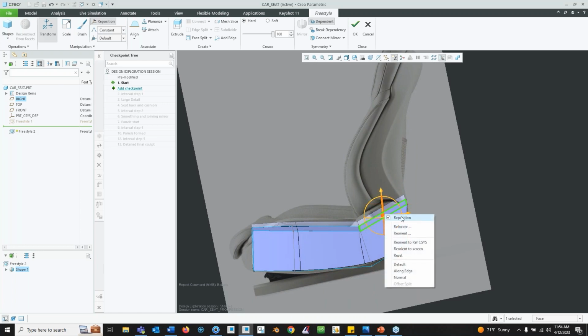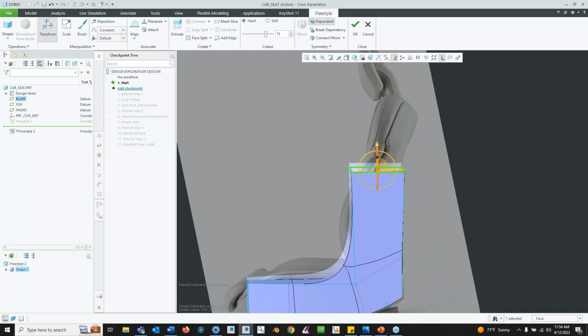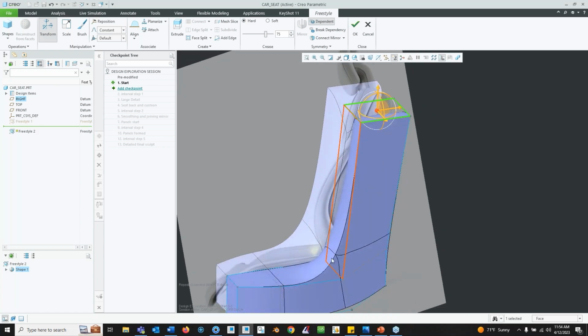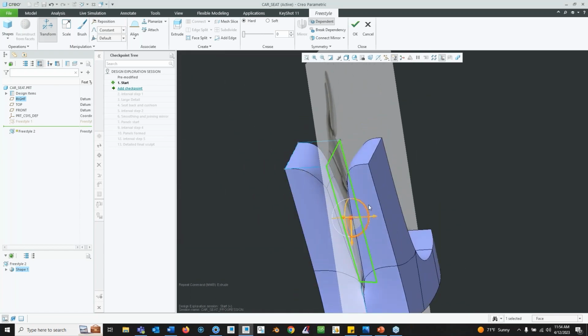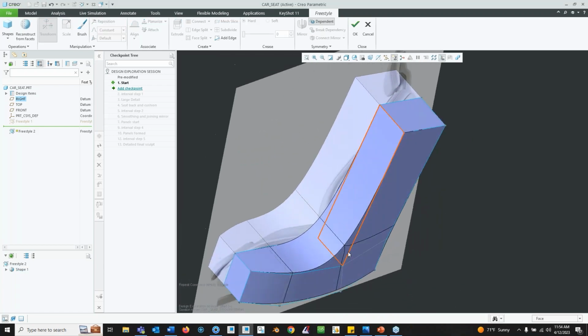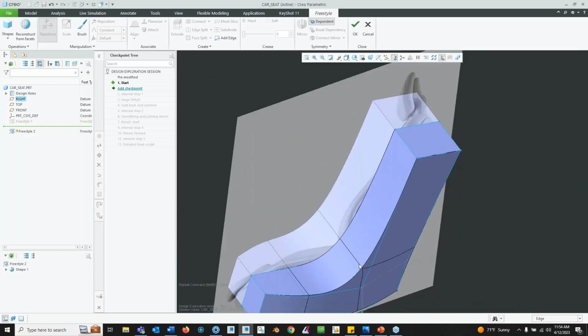And then if I click it again and uncheck it and I hit extrude, you can see I can start to pull and push this up. I could even go up all the way if I wanted to, at least up into the headrest point, kind of like this. Again, the center face, I'm going to delete that. You know, this edge, I might want to smooth that out a little more, or not smooth it out, but make it a little.